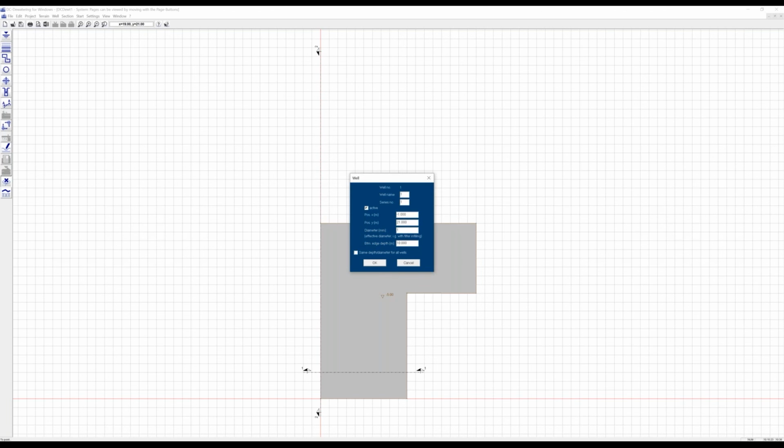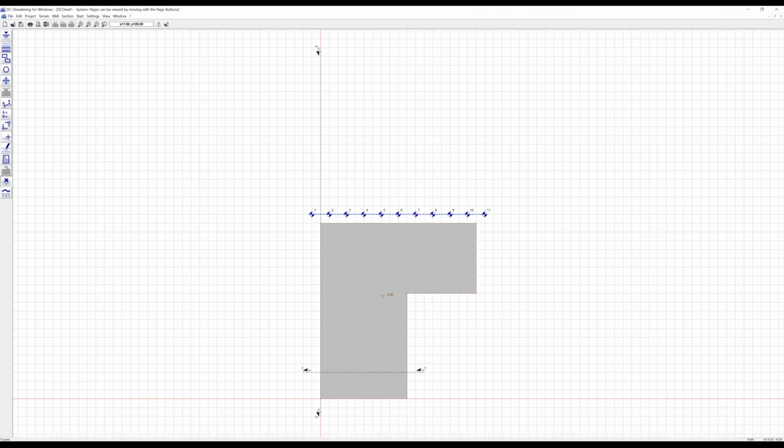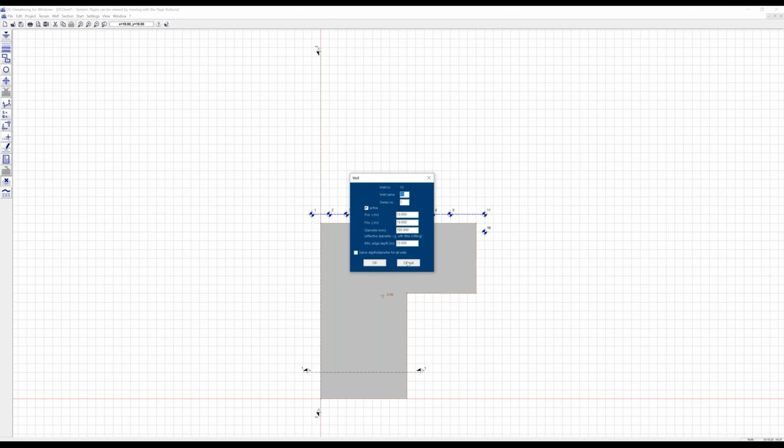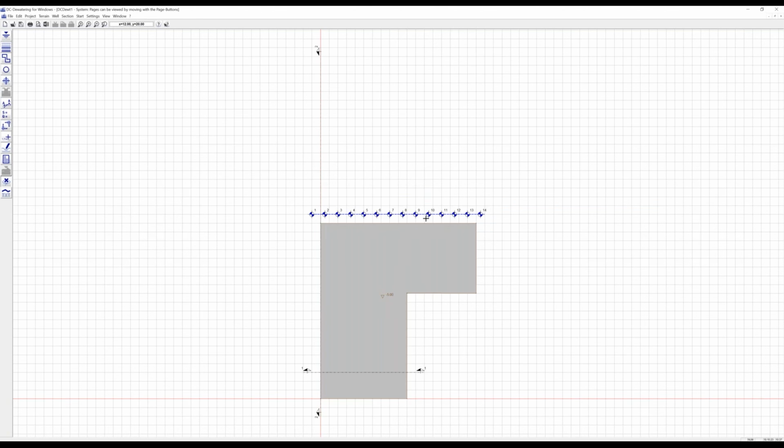with a certain diameter along this row. We can change single wells, we can move them to other positions, double click and enter the coordinates. But always if we change the row again, for example, if I use a distance of 1 meter and 50, all these wells are created again along this line. So this is an option if you have very many wells along a large foundation pit, for example.